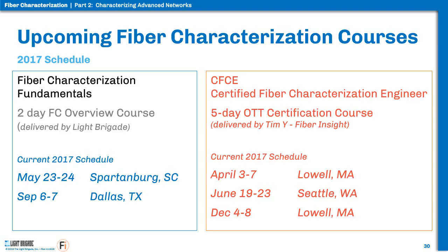That's a given. ORL isn't that critical on lower speed systems because lower speed systems can tolerate reflections better. But as you get to higher speed networks, ORL becomes much, much more critical. I think it reaches a point where it's just as critical as the insertion loss measurements, but you can't not do an insertion loss measurement. You could choose not to do an ORL measurement.